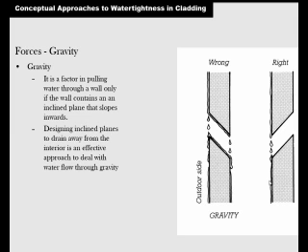When you have breaks in your finish, this is obviously the wrong way, because what does the water do? It falls down and, oh look, it just easily rolls downhill and inside. This one is the correct way because it falls down and it usually won't try to roll uphill. So you want your cuts to be beveled toward the outside. Whenever you're building something, think of how the water's draining. Just like when we studied roofing materials, you layer it from the bottom up so the water just goes down and never has a chance to go uphill.